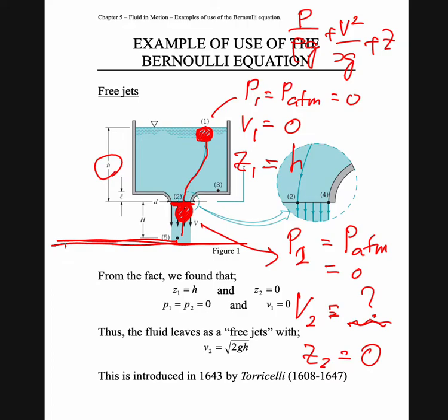If the datum is 0 and this is the positive side, then the height here must be H plus capital H, and then the Z here must be H. It is not 0 anymore because the height is measured from this new datum. So you need to be very specific about where your datum is.